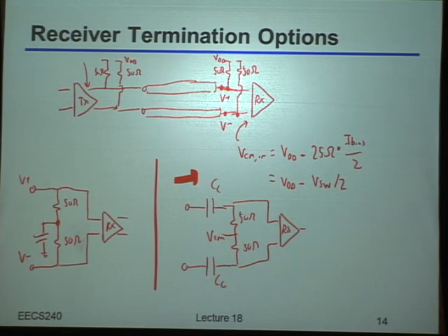Why don't I just arbitrarily do this everywhere? Yeah, you said the high pass corner. So what do you mean by that? Yeah, exactly. So what's going to happen here is that if I think about the transfer function of that circuit right there, as you said, it's a high-pass filter. And there's going to be some corner frequency below which I'm going to start attenuating my input signals.